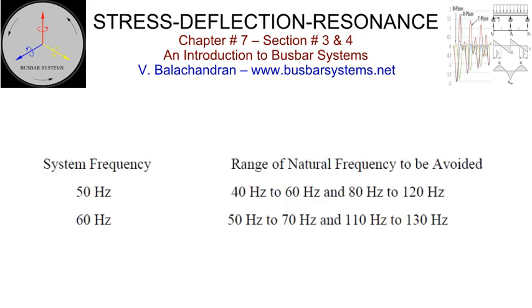It is necessary to ensure that the natural frequency of vibration does not resonate with the forced vibration induced by the short-circuit forces. For a given geometric shape and material of busbar, the only variable parameter to control the natural frequency is the span, which should be designed to avoid resonance. Following thumb rule may be followed to stay clear of resonant conditions.